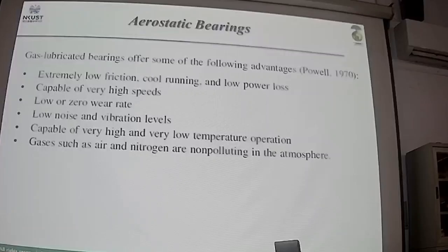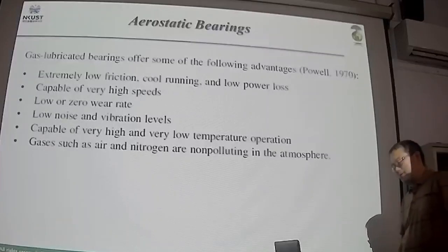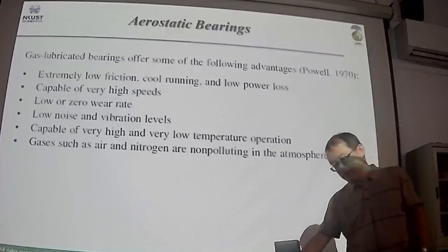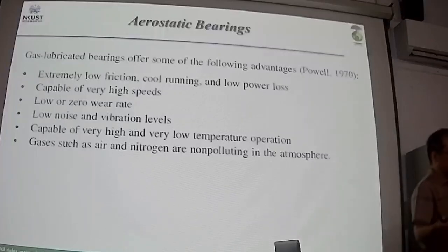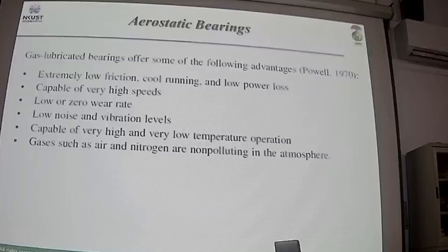Because for hydrostatic bearing, if you operate at rotational speeds bigger than 3,000 RPM, you would generate very high temperature in your lubricant. So you will have a problem of thermal deformation for the system.